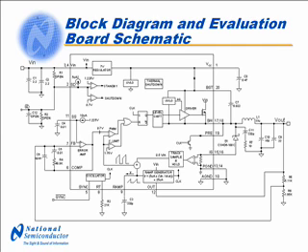Shown on this slide is the detailed block diagram of the evaluation board schematic for a 5 volt output buck regulator with a 3 amp current capability. The integrated buck FET has a 75 volt rating. The anode of the external diode connects to ground through the regulator's internal current sense resistor. This application operates at a switching frequency of 300 kilohertz.